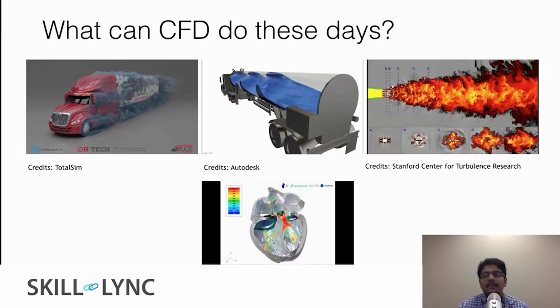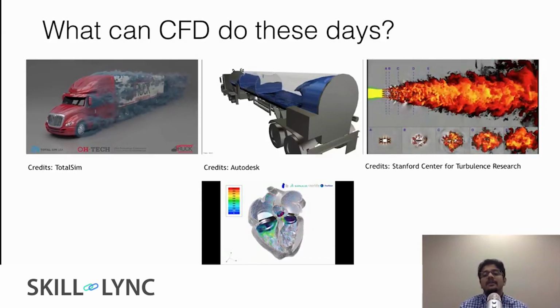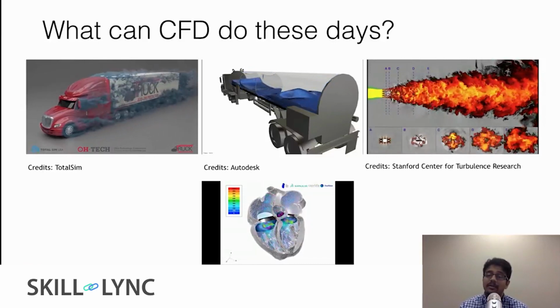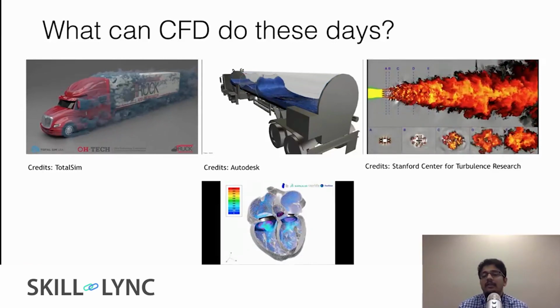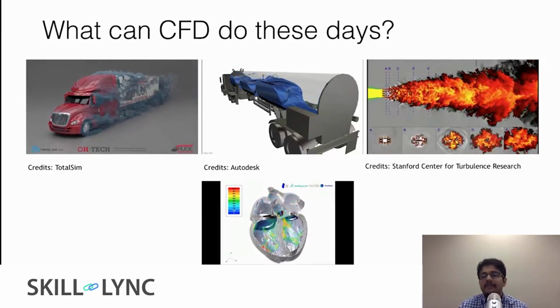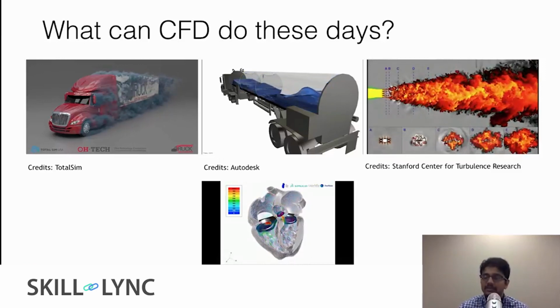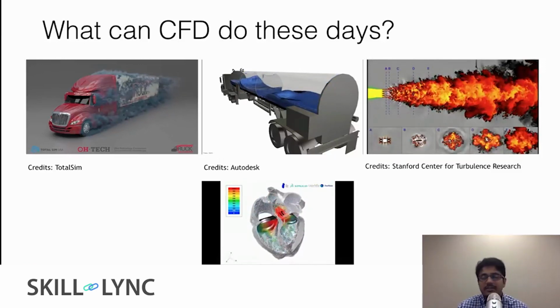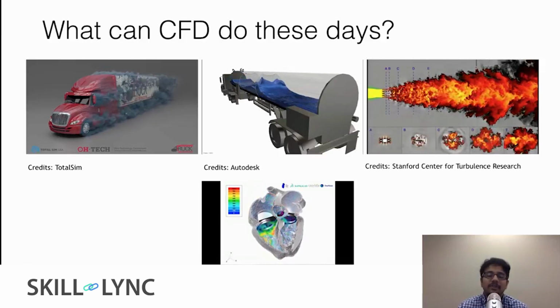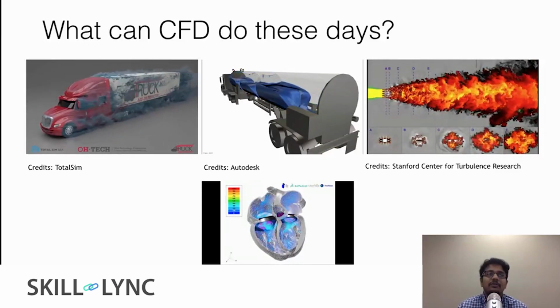With computational fluid dynamics, different nozzle designs can be evaluated, and then the residence time of the air-fuel mixture can be calculated or predicted. The whole goal of that study would be to maximize the residence time of the air and fuel mixture so that they mix well and hence the combustion is much more stable.